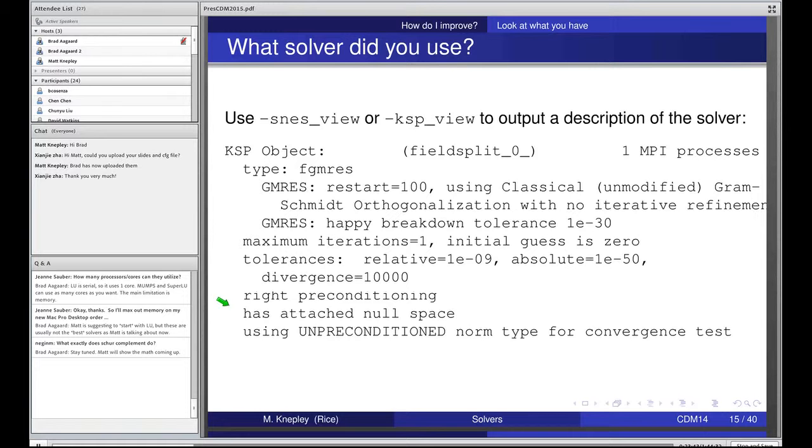So the question is, then, when you are building solvers for this, how do you tell the solver that you have this kind of degeneracy? Your boundary conditions remove this degeneracy in the full problem that you specified to PyLith, but the solver works on little parts of the problem, and the little parts of the problem have all these degeneracies, and it's only the full problem when it gets put back together with the boundary conditions that you remove them.